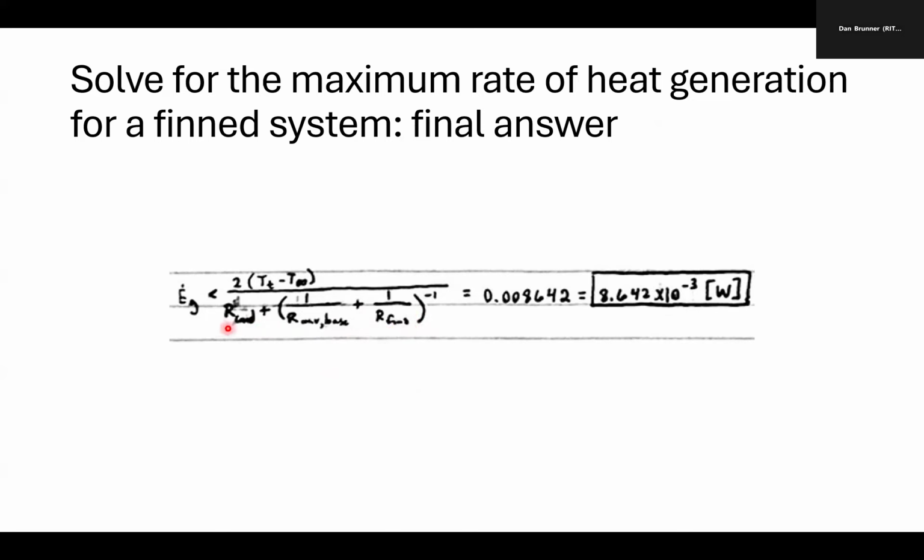The conduction thermal resistance is going to be exactly the same as it was for the first part without the fins, because that thermal resistance just goes through the silicon carbide layer that's surrounding the computer chip. Sorry, I guess it's not exactly a computer chip. It's just a little case of small electronics. But again, we have to multiply this whole expression by 2 because we have heat transfer going through both the top and the bottom.